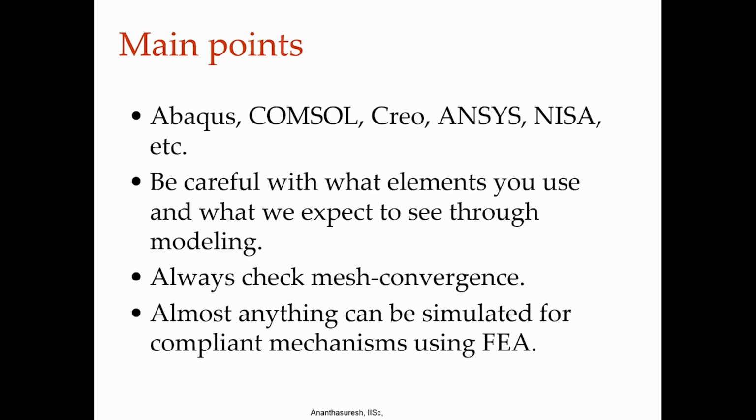And if we were to do 2D analysis of a 3D compliant mechanism, well, a compliant mechanism is always 3D because real ones will never be 2D. Some, maybe in modeling, we can do with 2D. When you use plane stress elements, we have to be careful. That particular paper that I cited reported that errors can be as much as 12%.